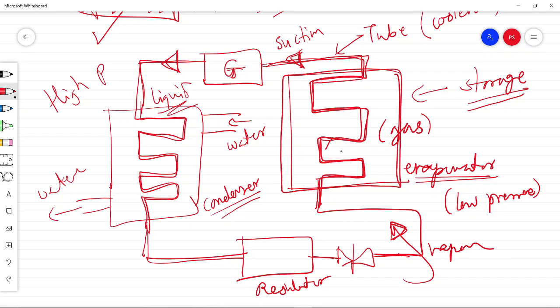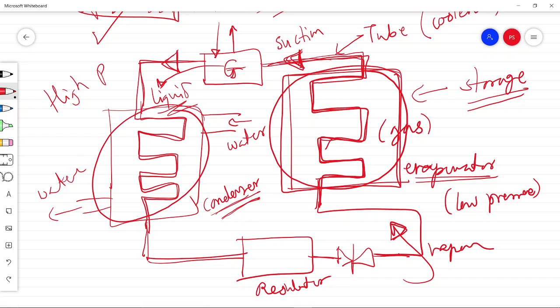So in this process, every time the compressor piston goes up, it sucks the gas, and when it goes down, it transfers the gas to the condenser region. During each such cycle, a very small fraction of heat is transferred from the storage region to the condenser region. So there is a net transfer of heat during each up and down cycle of the piston of the compressor, which extracts some heat from this region and transfers it to the other region.